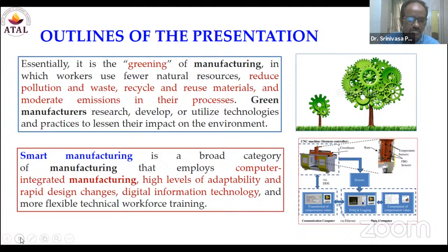If that particular program is understood and interpreted by a machine controller, and it repeats the task, whatever you are expecting it to repeat, the operations of 3 different axes or 2 axes or 5 axes in some cases, that is called execution of the part program. If it is done with the help of only NC part programming, that comes under numerical control. If it is extended beyond the NC part program, that comes under CNC manufacturing, CNC machining.